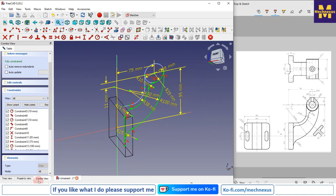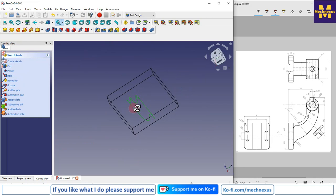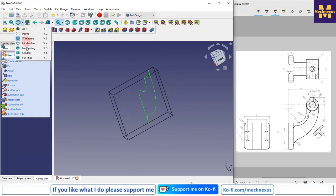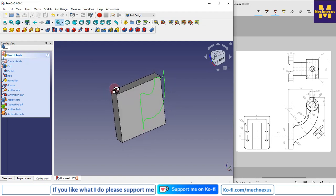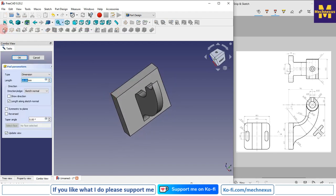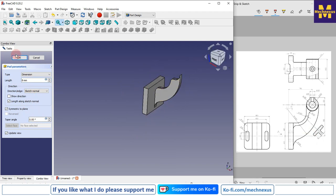Now we will come out of the sketch, and we will switch to the flat lines, and now we will make a pad. We will keep it symmetric to the plane, and its thickness is given here in the section as 8 mm. So I will give here the 8 mm, say OK,